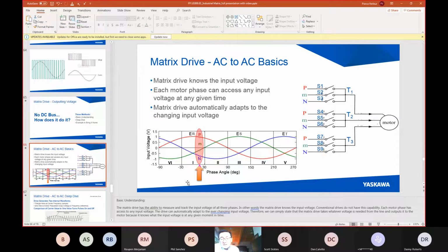That's not relevant to this discussion. What's relevant to this discussion is I'm unwinding and I'm winding up. The winder is going to pull power from the line as it tugs the material from the unwinder that's resisting that pulling force. And therefore, the unwinder is going to regen. When I do winder-unwinder with a standard PWM drive availability, I just connect the DC buses. When I do that with the matrix drive, that power circle is completed through the line itself.